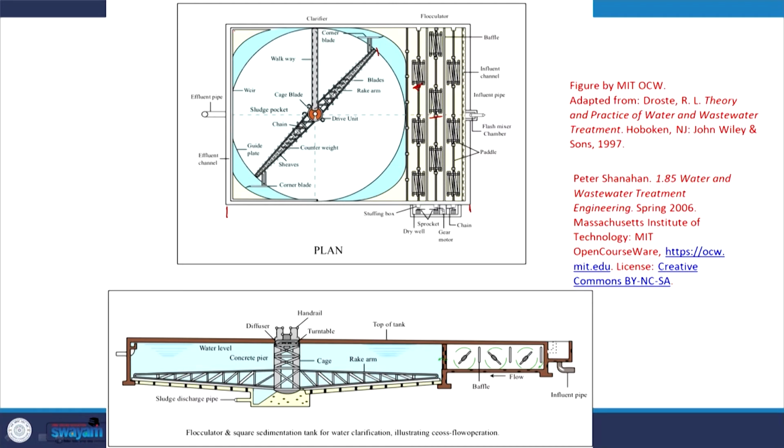And one issue here is that obviously you have dead zones out here, so removal of the sludge or particles that have settled out here is an issue. And looks like due to the weir length along these particular edges, you can have radial flow or non-uniform flow affecting your removal efficiency. So that's one aspect to consider.